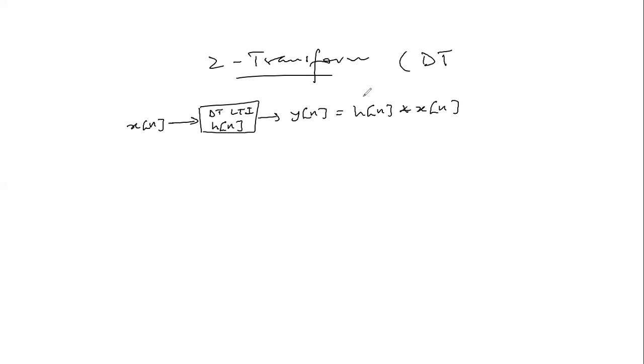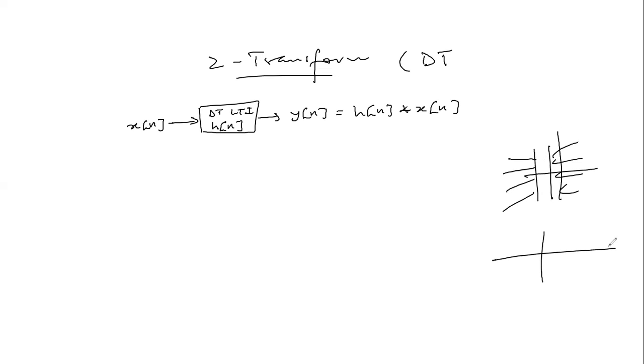Or we could also get a null. So it's either it closes in if we have a right-sided, left-sided closing in. At times the region of convergence could spread out and not spread in, depending on the condition. So you want to be sure what you are looking at, the positioning of the right-sided and left-sided signal. If the positioning of the right-sided and left-sided signals are in the opposite direction, you may get a strip that looks something like this. But depending on the positioning of the right-sided and left-sided signal, you could get something that looks exactly like this. So you have to observe those differences.